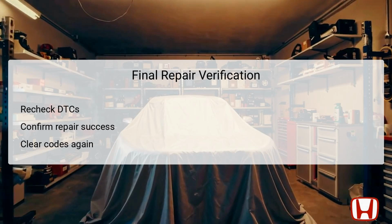After completing the necessary repairs associated with DTC P0882, it is essential to verify that the repairs have been successfully executed. Begin by rechecking the DTCs using the Honda Diagnostics System, HDS, ensuring that DTC P0882 does not reappear. This verification step is crucial, as it confirms whether the issue has been resolved or if further action is needed. Following a successful check, clear the codes once more to reset the vehicle's systems completely.